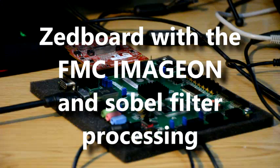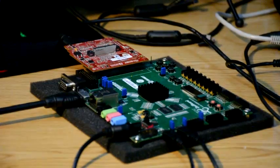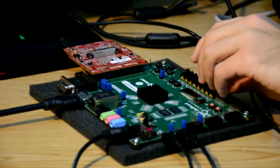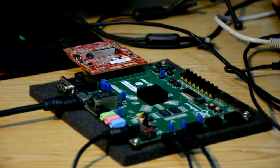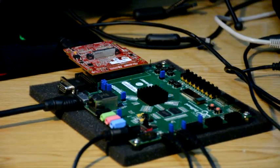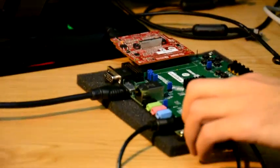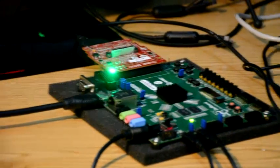For this demonstration, I have set up the Zedboard FPGA. First of all, we have to make sure that the configuration of the switches is well placed for reading from the SD card that is below the FMC expansion card. That expansion card is connected through HDMI to a camera. This one is the Sony HDR-30V.